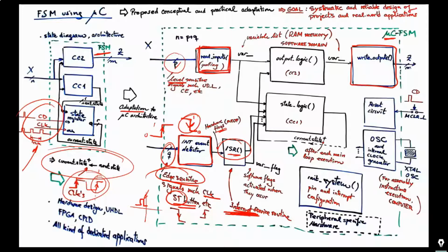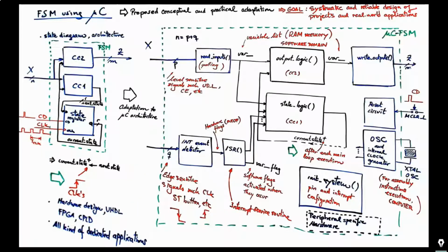First of all, because this event detection means that you have a special hardware, okay? In the same way that when you read inputs or write outputs, you can do that because you have in the init system the possibility to establish the pin direction, by means of the TRIS registers that set the pin direction. Here, if you would like to detect an event, this edge of a given signal, you have to be able to introduce this hardware, but not for all the pins of the computer ports, only for some of them.